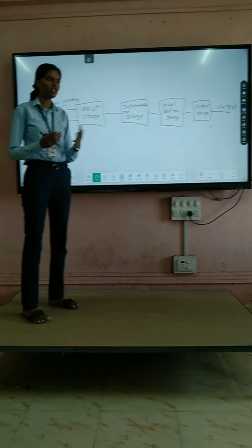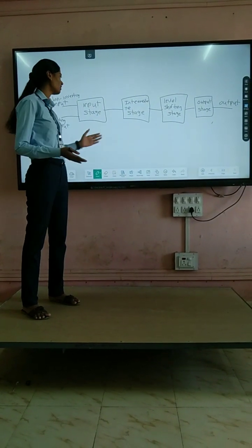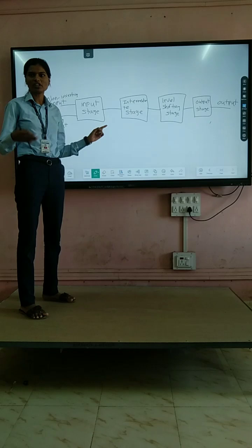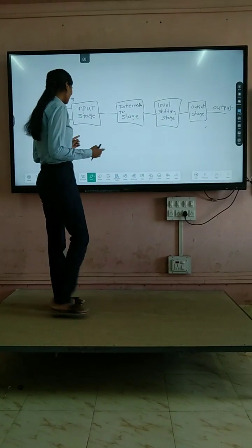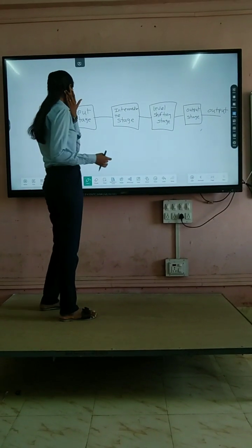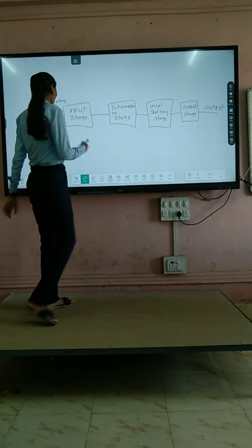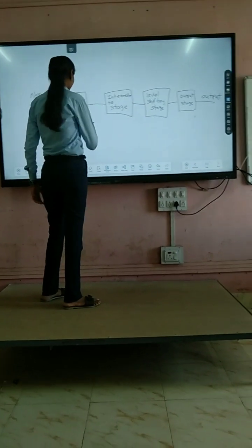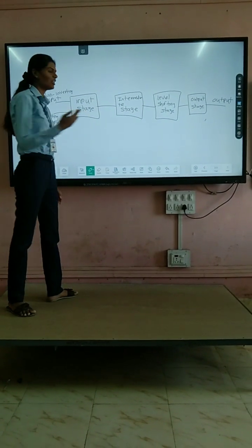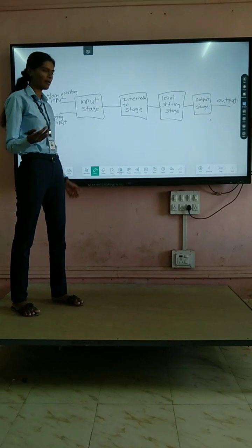The input stage is a dual input, balanced output, differential amplifier. It provides the voltage gain of the operational amplifier and establishes the input resistance of the operational amplifier.